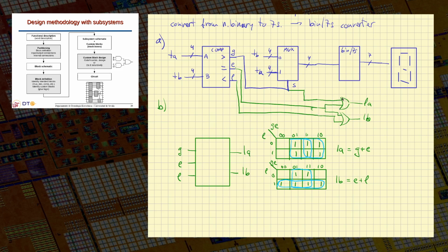We may have arrived at that solution just by understanding what's going on. But even if you don't have very clear the dependency between the outputs you want and the data you have, you see there are many options. If the number of signals is not very big, you can always do it as a general problem and use a Karnaugh map, and you will be sure that you will get an optimum design for that. Okay, so that solves our problem in that case. Of course, you can solve this part using other options, maybe using a multiplexer, maybe using a decoder and some gates, any way you may think about. But I think it's a convenient and clear enough option to solve the problem. Okay, that's it. Thank you.